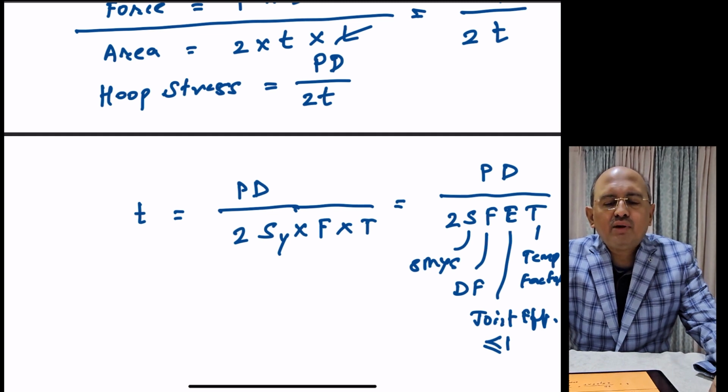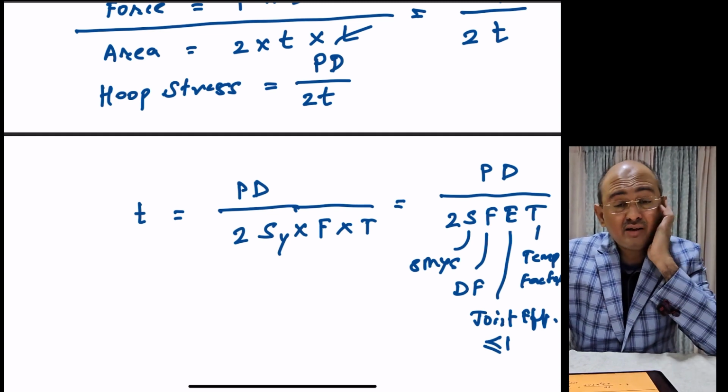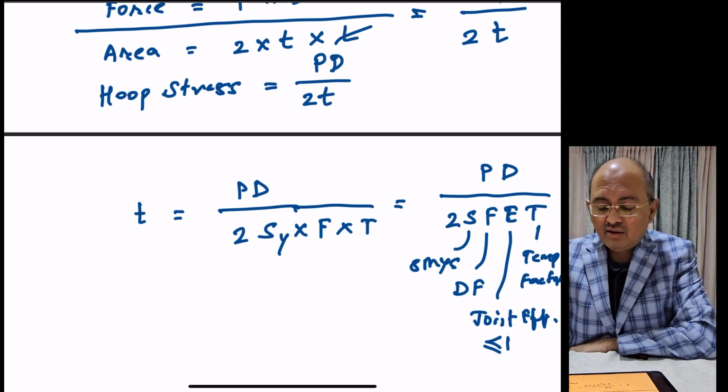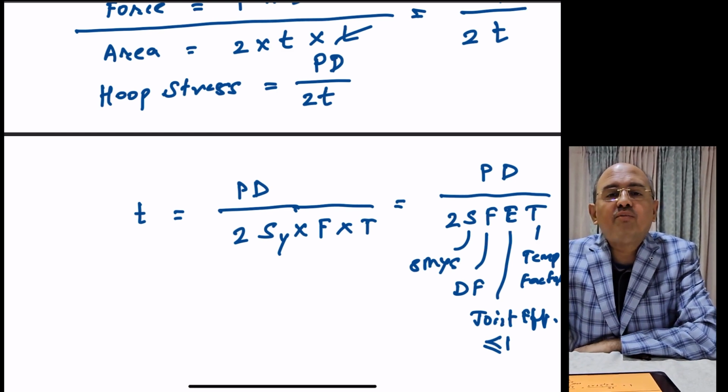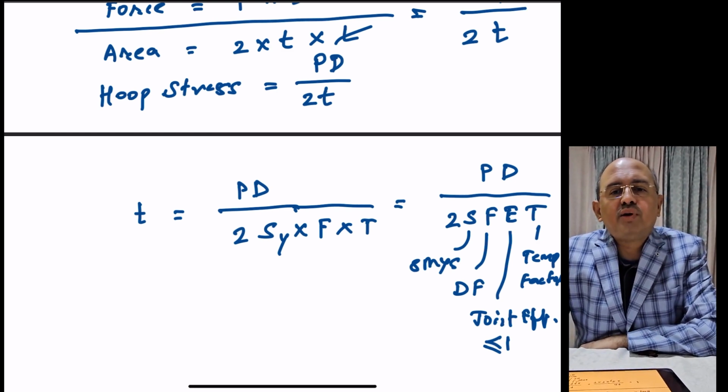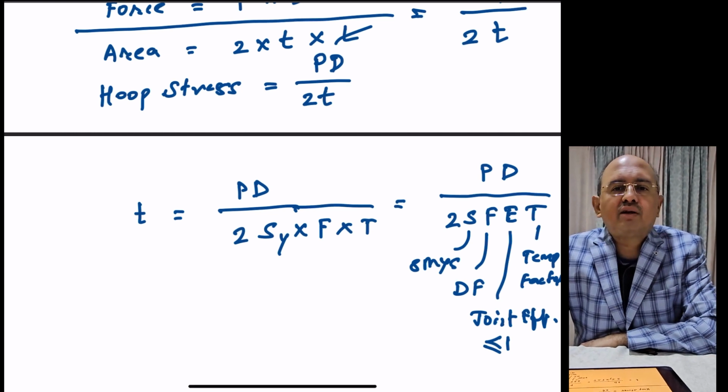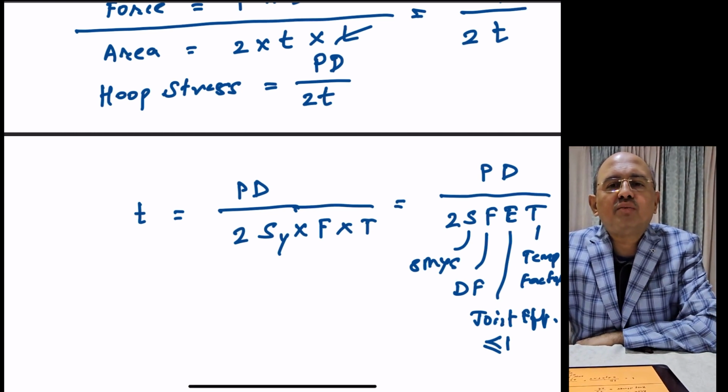It's nothing but the material strength reducing on heating. The same thing applies here. So if your pipe is going to experience very high temperature, then its strength will be reduced to some extent, so accordingly you have to add additional thickness margin for that. That is the reason this factor is coming.